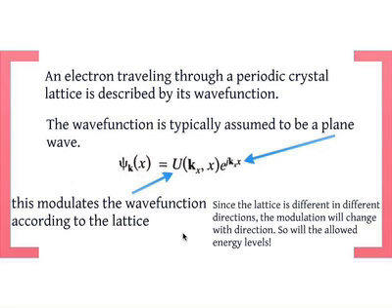One important consequence of this assumption is that we know that the lattice is different in different directions. Remember, last Tuesday we talked about the different crystal lattices, and as you saw, especially in silicon, as you rotate them, they look different. 100 is different from 111, and so on, which means that the potential that the electron wave will see will be different in different directions.